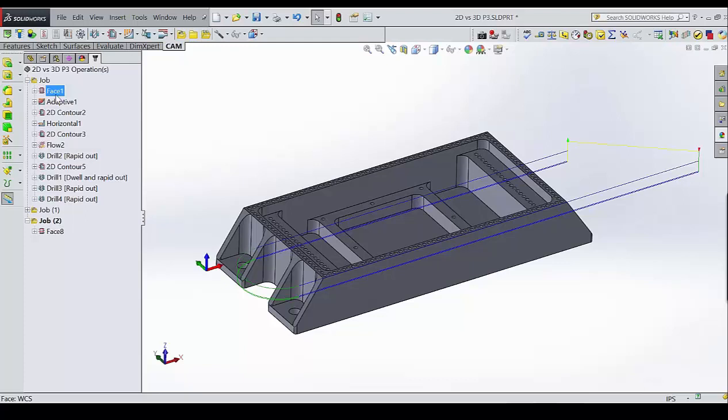I'll set it up at 25% of the tool diameter, and then fully retract after it gets to, say, 4 times the tool diameter. So we can go over that. But does that answer the question? It does, yeah. And then Chris responded, thanks. So that answers his question.